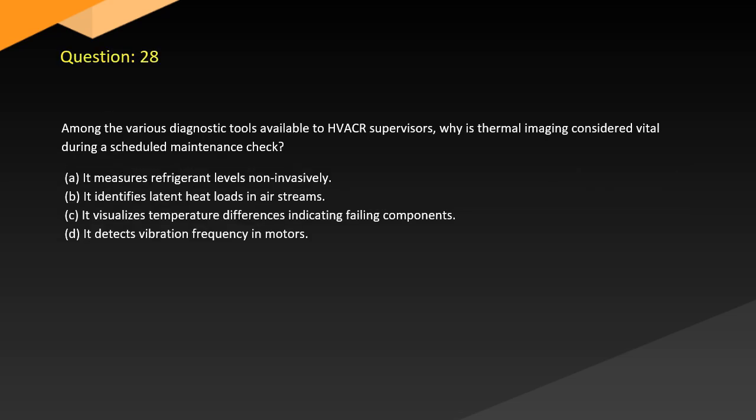Question 28. Among the various diagnostic tools available to HVACR supervisors, why is thermal imaging considered vital during a scheduled maintenance check? A. It measures refrigerant levels non-invasively. B. It identifies latent heat loads in airstreams. C. It visualizes temperature differences indicating failing components. D. It detects vibration frequency in motors.